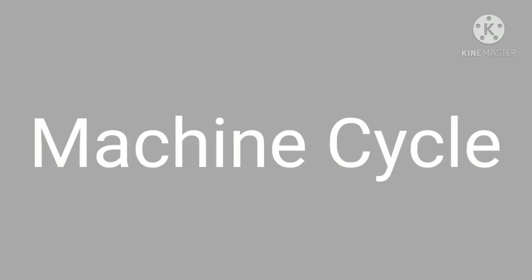Next, machine cycle. What is meant by machine cycle? It is defined as the time required to complete any operation which is a subpart of an instruction. The machine cycle may consist of a number of T states. For 8085, a machine cycle may consist of 3 to 6 T states, depending upon which machine cycle operation is being carried out. This is known as machine cycle.